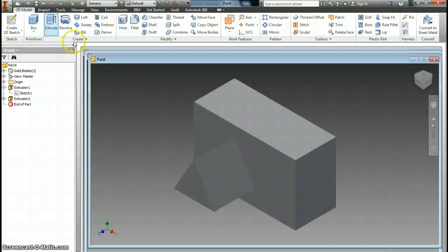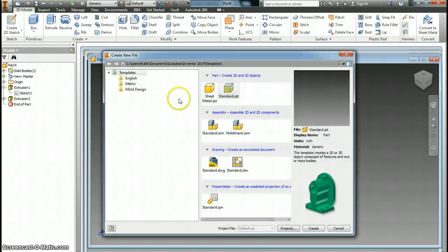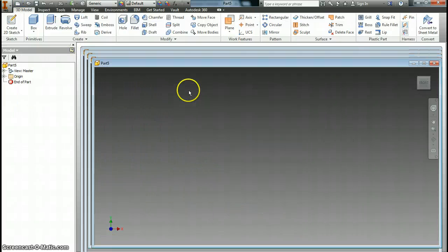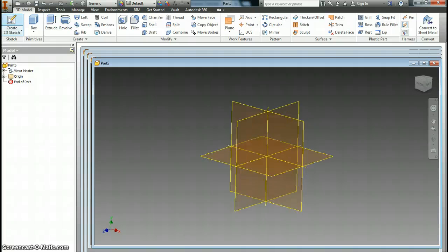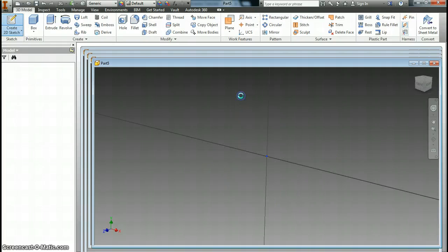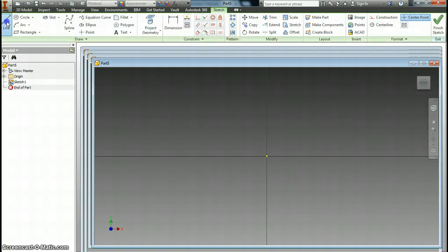First thing we'll do is open a new Inventor part file, and we'll start a sketch, and we'll do the front face, and we're going to design a trapezoid. So using the line tool, we'll create something that looks like that. And then I'm also going to just drop a vertical line over to the side. I want to make sure it's vertical, straight up and down. It's parallel to the other line. Then I can right click and hit OK.